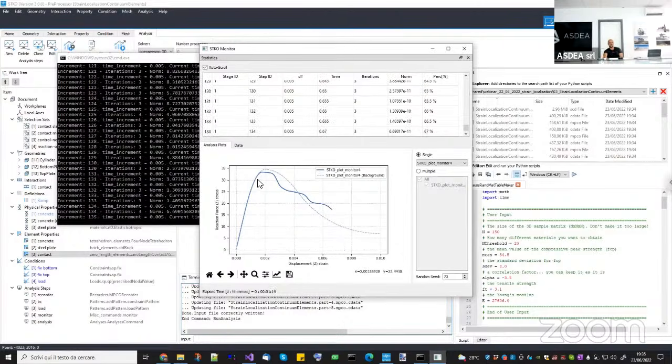You can see that this kind of model, which seems very simple, is actually very complicated if you don't know how to treat the problem of fracture energy, the problem of how to trigger localization in a constant state of stress, and how to correctly model boundary conditions. Because when you do a frame model, it's very easy to place boundary conditions. It can be either fixed, pin, or whatever.